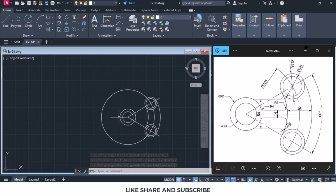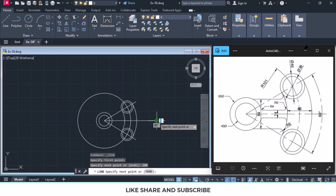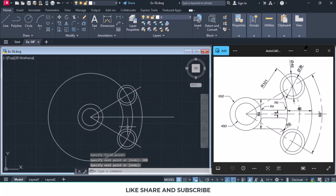Now we'll draw one center line. So we'll select L for line. We click over here and we draw a line up to here, something like 200 units. It can be of any length, and press enter to come out of the line command.